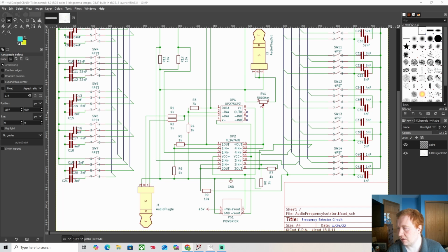So this one is up to 9 megahertz of gain bandwidth, which is plenty for our purposes. It only takes 4 milliamps to power it, so again, fine. The current output per channel is 90 milliamps. The supply voltage goes from 9 to 44, minimum, maximum.